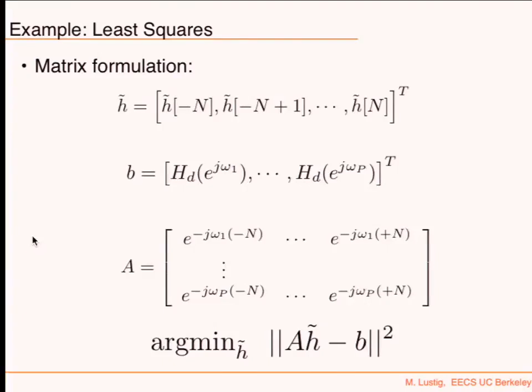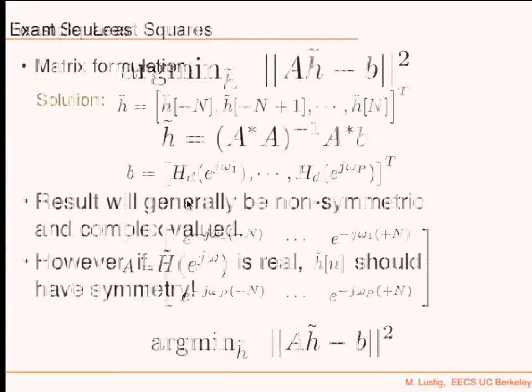Okay? And what will be in the stop band? It will be zeros. So B would be a vector of 1, 1, 1, 1, 1, 1, and then 0, 0, 0, 0, 0, 0. That's it. And then this is basically just complex exponentials with different frequencies. Frequency 0, frequency 1, and so on and so forth, till we finish the passband, then we go to the stop band, and that will be almost pi. Omega sub p would be the one closest to pi. All right.